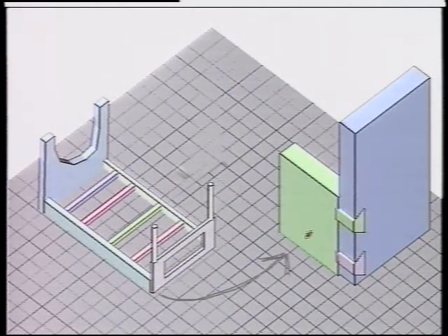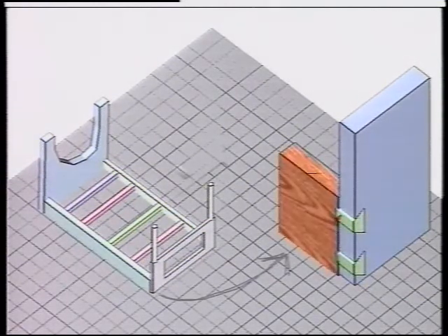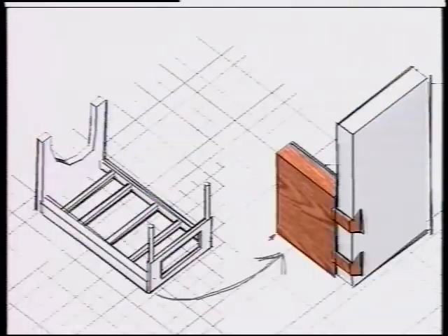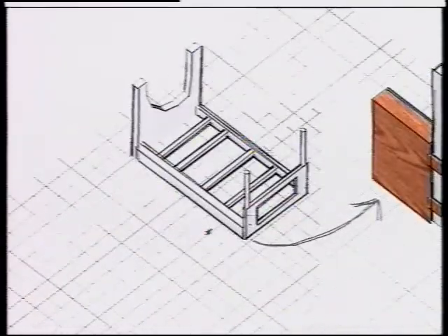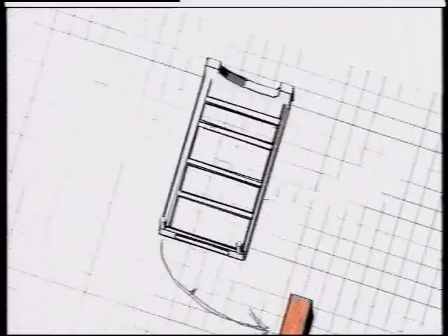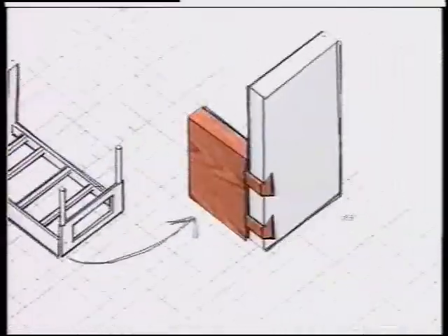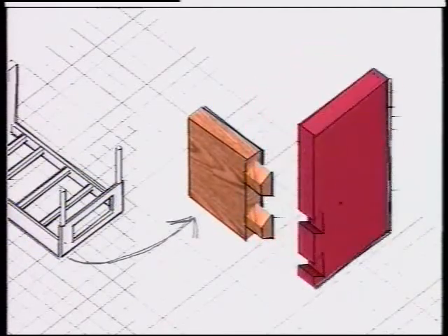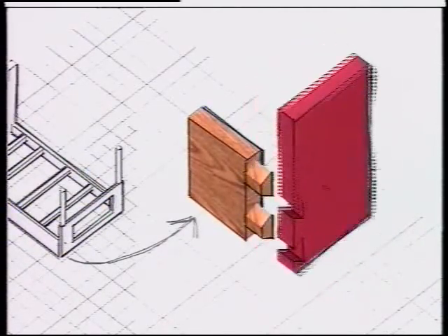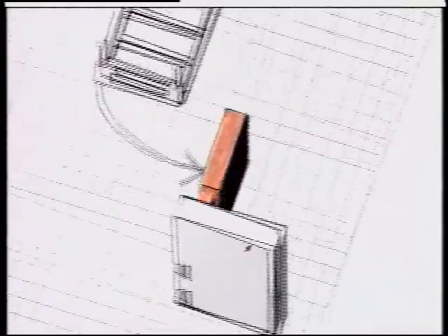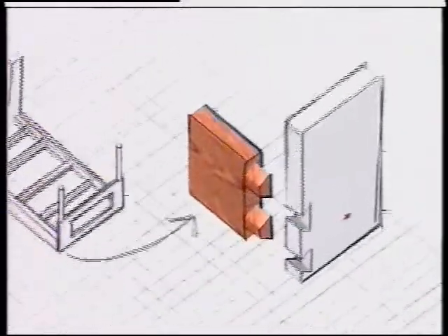To apply colors and textures, we simply type their name over an object. To make our illustrations more expressive, we support a variety of rendering styles, including a non-photorealistic black and white sketch. Throughout the video, all drawing operations are done with only the first mouse button, all object transformations are performed with only the second, and all camera manipulations with the third. A single modifier key is used for secondary operations like copying colors and drawing schematic elements.